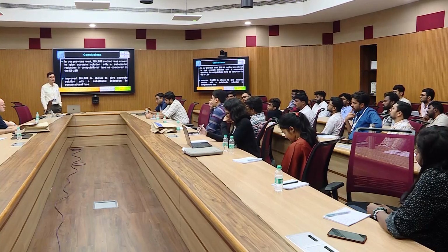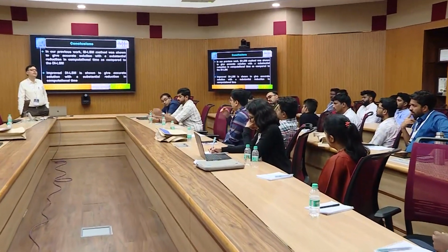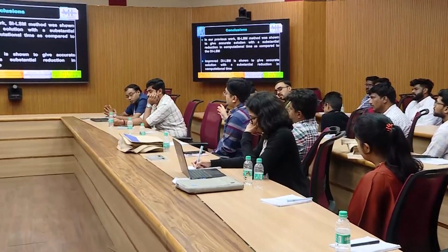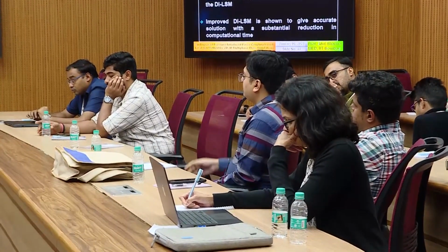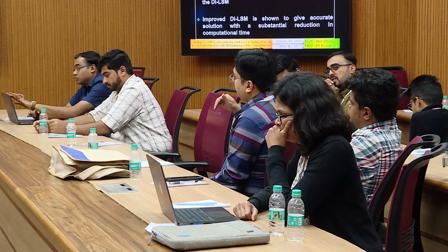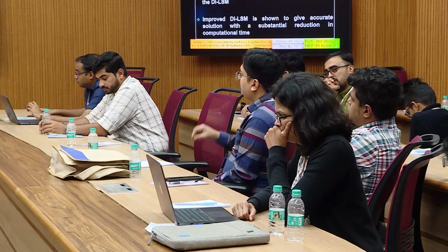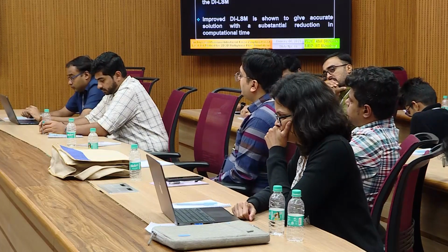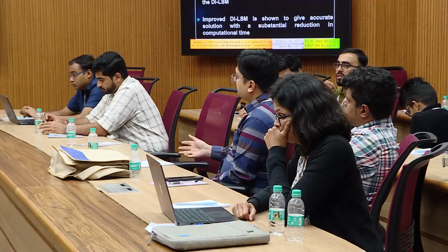So I have another question. You have compared these three methods in terms of the mass error. But there's another thing always in commercial multiphase codes, which is spurious currents. When we have a very sharp curvature or a triple point being formed where the interface is contacting the surface, there are always spurious currents. So in terms of spurious currents, how do these three methods differ, good, bad, or different?